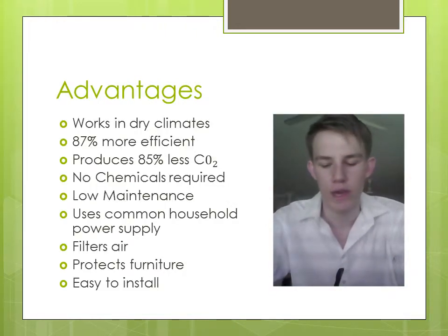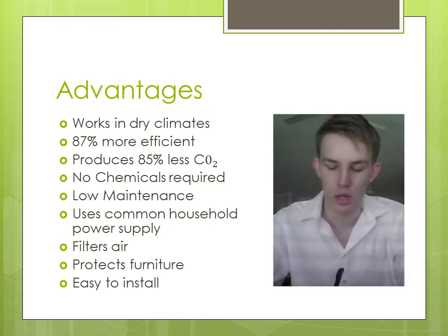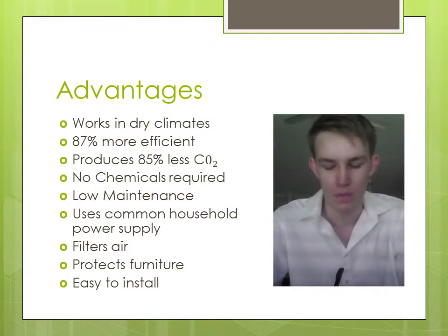Advantages. The first advantage of evaporative cooling is that it's designed to work best in hot, dry desert climates. It requires 87% less electricity compared to other systems, which lowers the running cost accordingly. It produces just 15% of the CO2 emissions that would be produced by other system types, which is much better for the environment. It does not use chemical refrigerants such as CFC and HCFC, which improves its environmental friendliness.